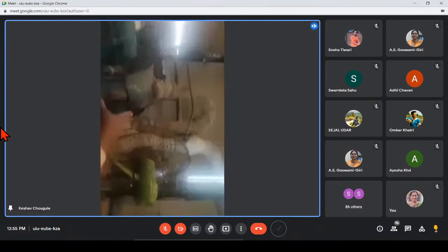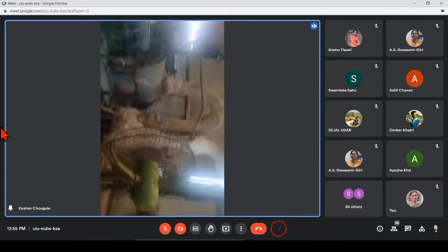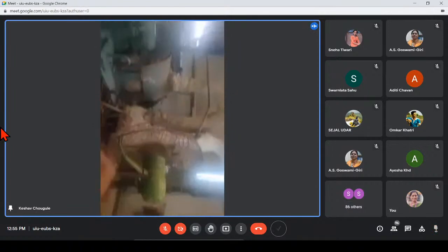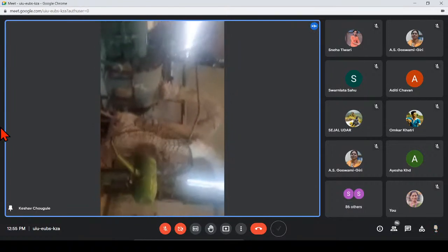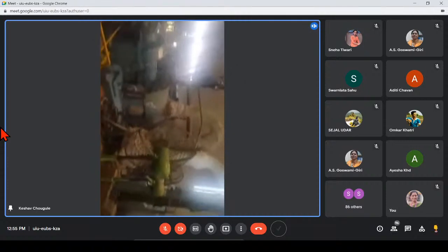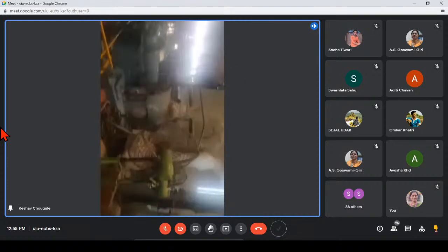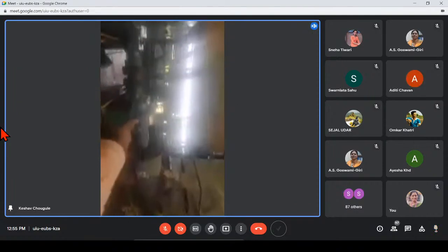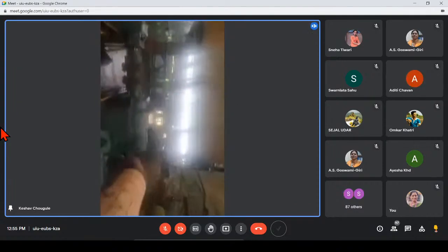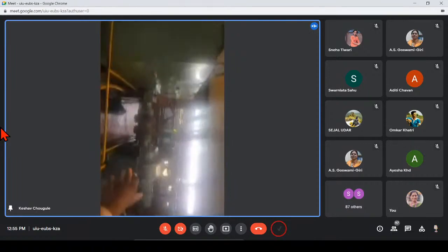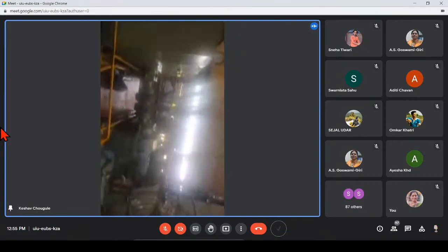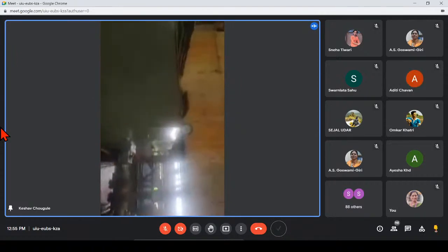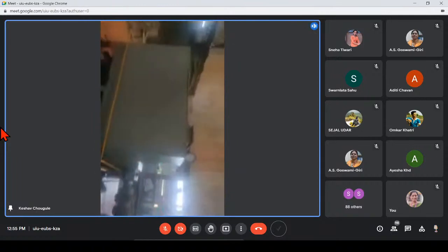There is a steam turbine. The high-pressure steam coming from the boiling section strikes the threaded blades of the steam turbine. Due to that, the steam turbine starts rotating at up to 6,000 RPM. Using a gearbox, we reduce the speed of the steam turbine and take only 1500 RPM of supply rotations, which are given to the alternator.